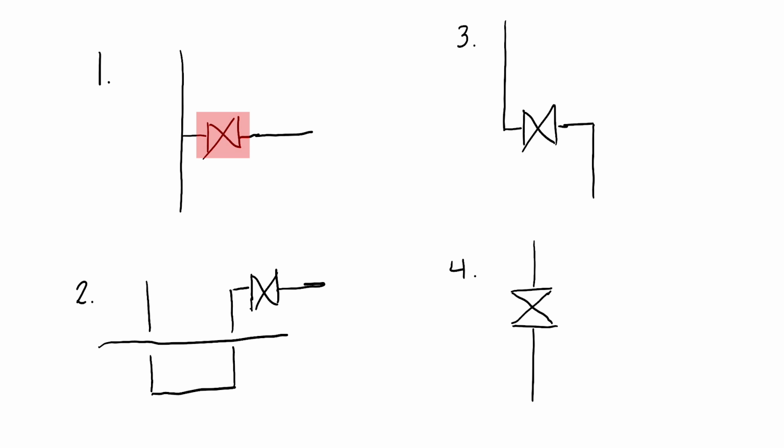When we talk about arrangement, this is what we mean. We are depicting what exactly is in the field because there's a branch in the piping. So that's going to be important for pressure drop calculations, for failure calculations when we're looking at our HAZOP where that valve is. What's not quite as important is in 2 and 3.